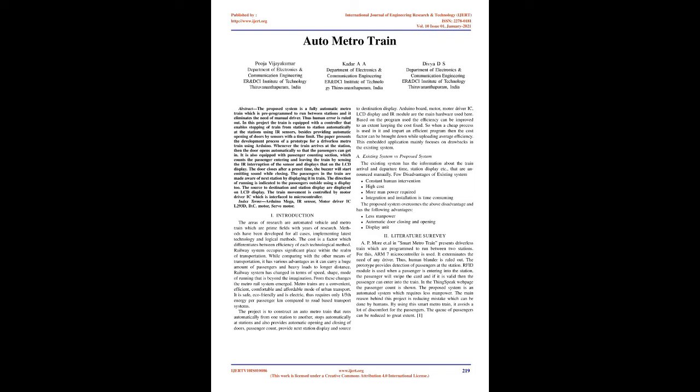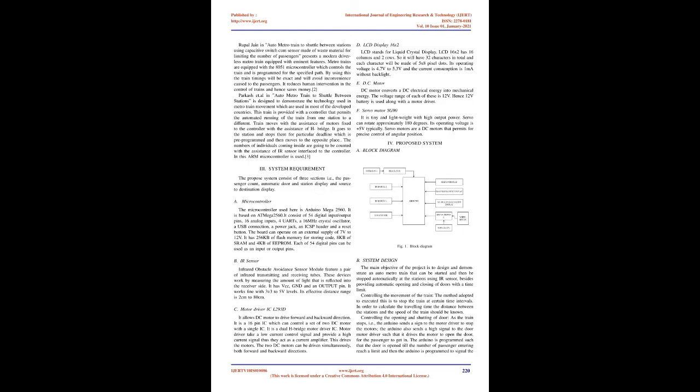4. Place the plastic wastes into the foundation roughly and equally. 5. Over that plastic waste, M.Sand or sand shall be poured in the foundation. 6. By ramming the plastic waste and M.Sand or sand mix, the surface is ready for providing plain cement concrete. 7. Over that, P.C.C 1:4:8 shall be laid by usual methods. 8. From the above procedure, plastic wastes can be used.